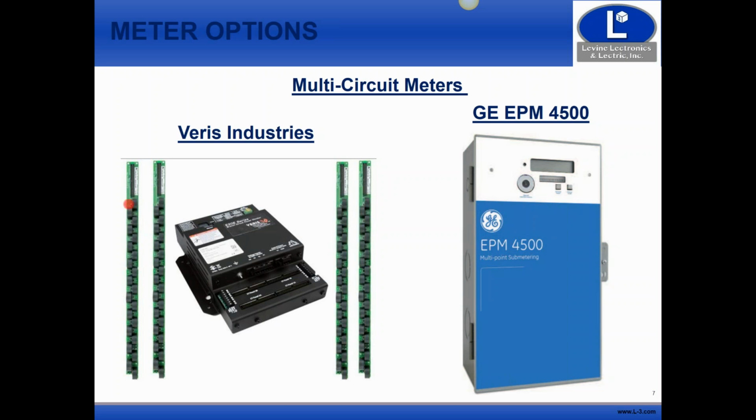You actually can monitor each individual circuit. You've got CTs here for each individual 120 volt circuit. Okay, so if it's a 3-phase, you've got 3 of them, it covers all 3 of them. If it's single phase, then it separates all of it out at an actual circuit standpoint. These CTs are on these PCB boards right here. They're mounted in the panel board, and when the contractor wires this up, they bring their wire down and go through the CT and hook it into the breaker.